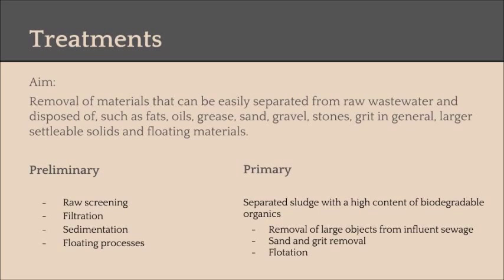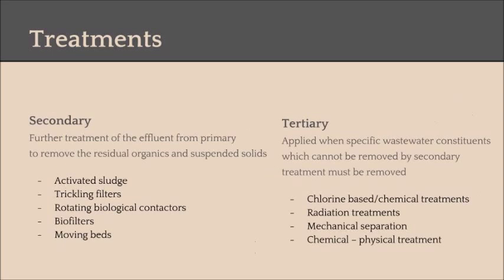Here we introduce different treatment classifications. Water treatments can be divided into preliminary, primary, secondary, and tertiary. The aim of the preliminary and primary treatment is the removal of materials that can be easily separated from raw wastewater and disposed of, such as fats, oils, grease, sand, etc. The secondary treatment removes the residual organics and suspended solids. The tertiary treatment is applied to remove specific wastewater constituents which cannot be removed by the previous treatments.